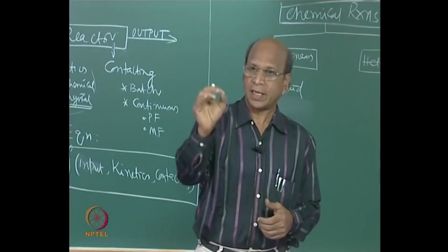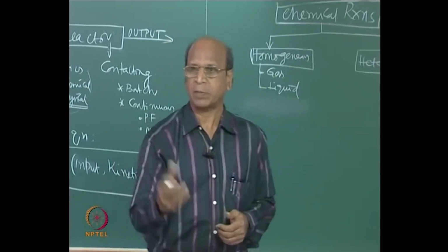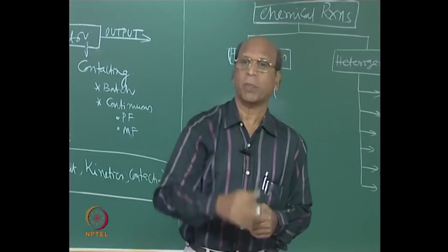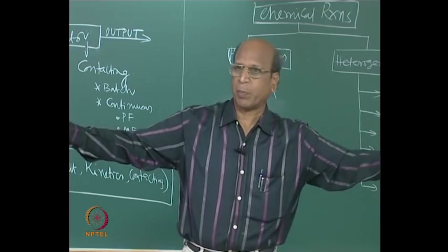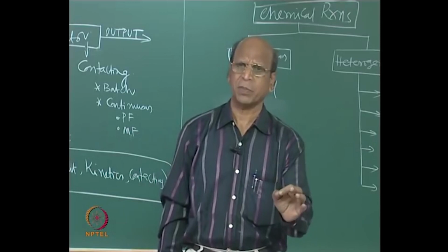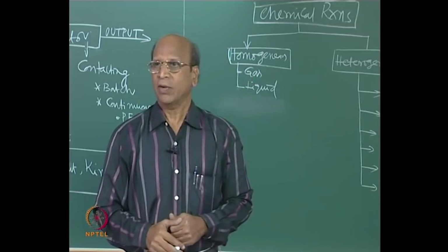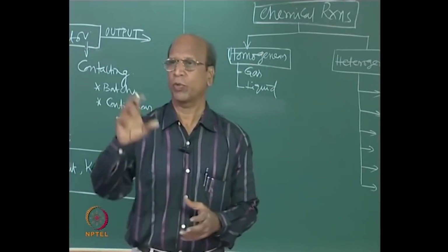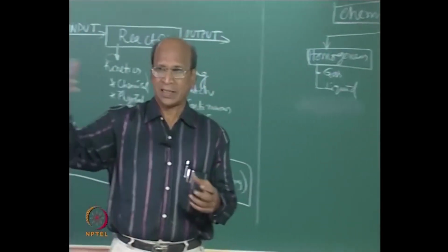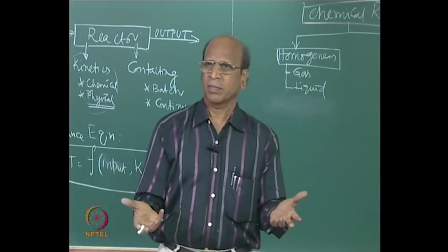That is why we take either 1/4 inch, 1/2 inch, that means maybe 12 mm, 10 mm, 8 mm, 6 mm, that is what particles we use. But if the reactor diameter is slightly bigger, then normally we go for a maximum of 18 mm, that is 3/4 inch. Okay? 1 inch also, as far as I know, no one in the industry will go for, because we are losing surface area, that is mainly the reason.